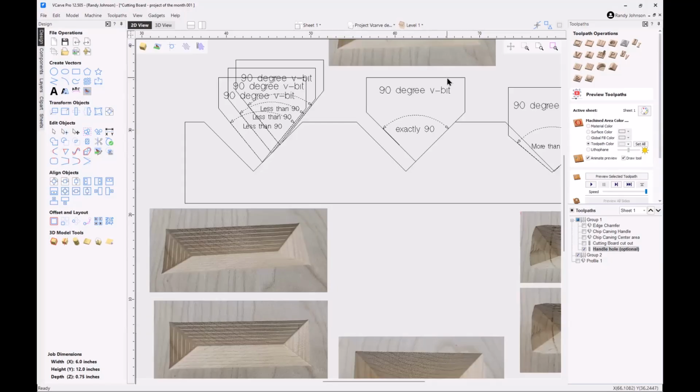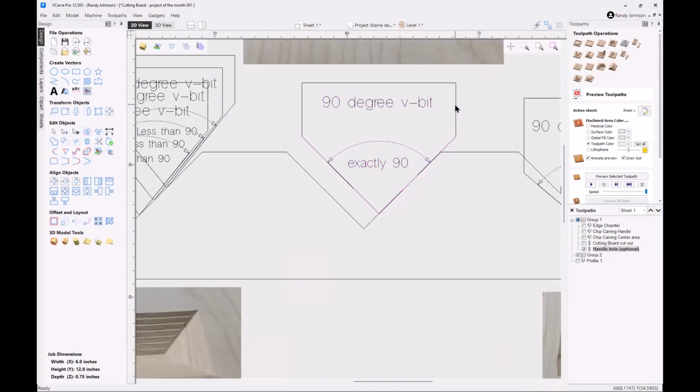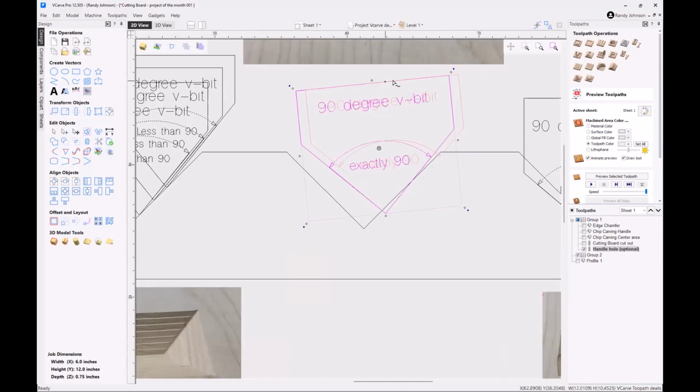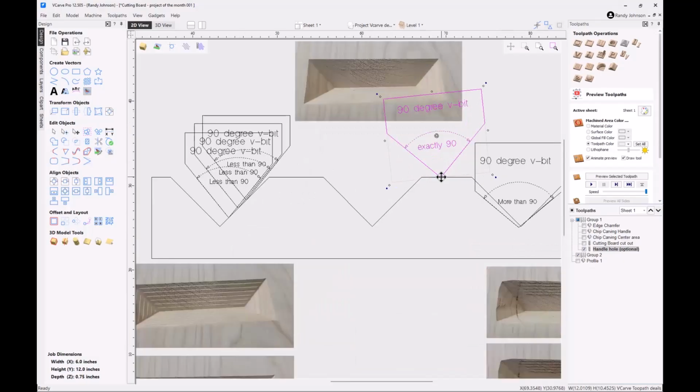Another option that could occur, which is a little more serious, but is potentially solvable, is let's say I'm going to take this, let's rotate this, exaggerate. If your spindle is not plumb to the table, it's not going to spin on center either. So tramming the router, which is information out there, we'll go over that one of these meetings on how to true the router to make sure it's perpendicular. That's another thing that could cause it.